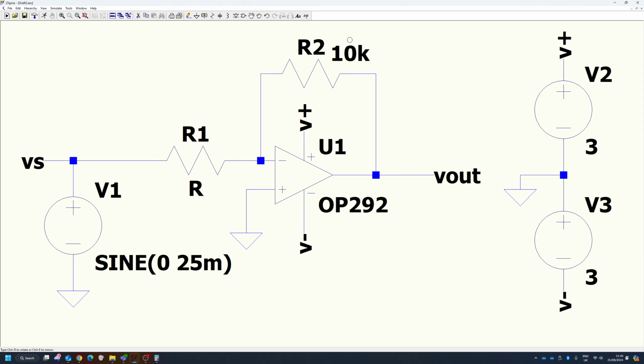Let's grab this guy, move it up here so it doesn't conflict. And if I type 2.2K or 2K2, that's exactly the same thing. That's how we usually put things into circuits. The same thing goes for mega and so on. So the circuit is ready, I believe.